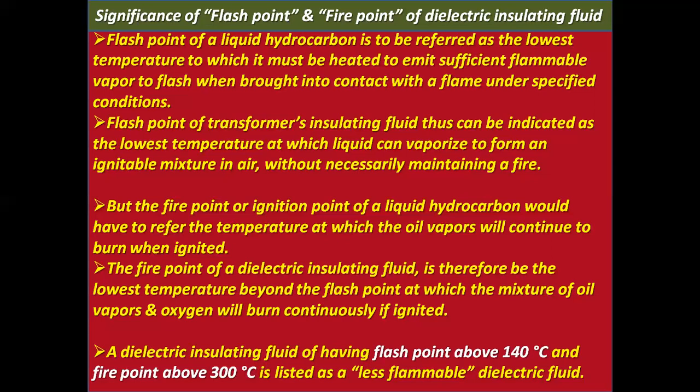A dielectric insulating fluid having flash point above 140 degrees centigrade and fire point above 300 degrees centigrade is listed as a less flammable dielectric fluid. Again, I repeat, such a fluid is listed as a less flammable dielectric fluid.